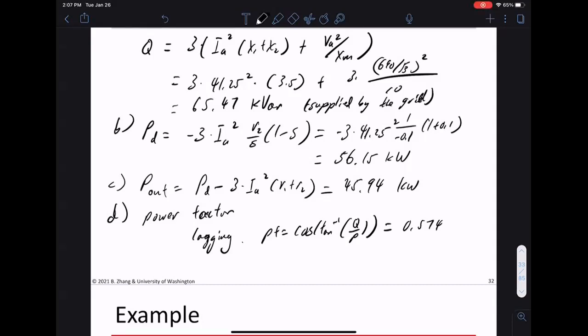Because you need power to the stator windings in order to have it work as a generator at all, right? You need a synchronous frequency. You don't necessarily need power, you basically need a frequency. If somehow you can provide the frequency with very little power, it could work. But that's also a problem: who's going to provide a synchronous frequency? Your fridge is not going to provide synchronous frequency.